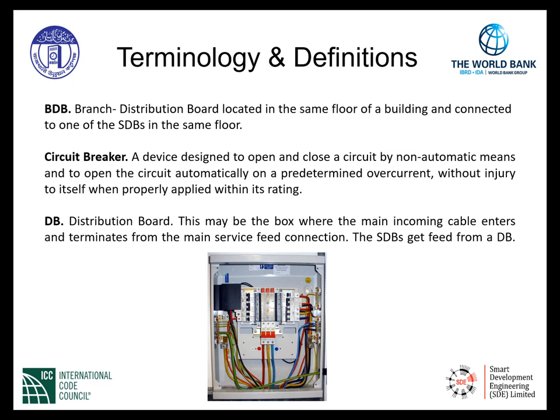Circuit breaker is defined as a device designed to open and close a circuit by non-automatic means, and to open the circuit automatically on a predetermined overcurrent without injury to itself when properly applied within its rating. Circuit breakers are used for protection of our conductors that supply electrical power to equipment and appliances utilized within our buildings. The term DB, distribution board.